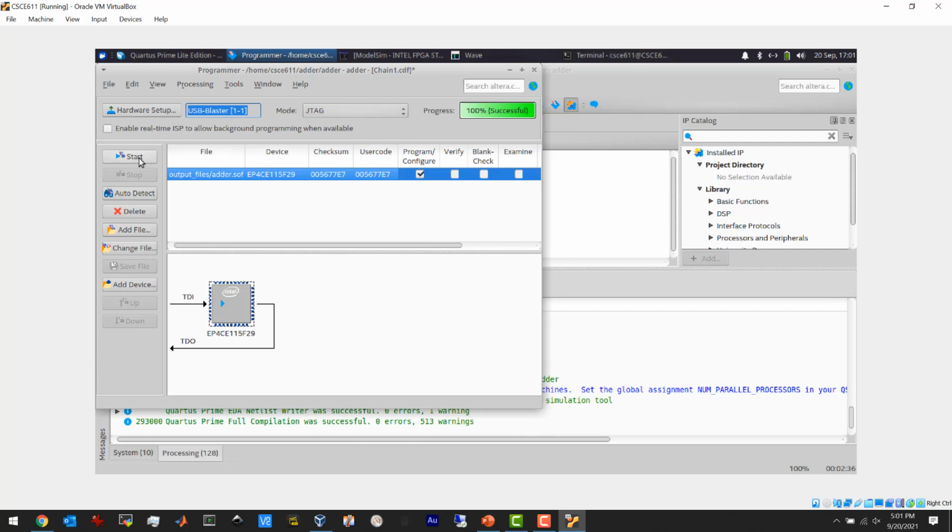Okay, so I'm going to flip switch 9 and 8 because those are the two least significant bits of A. And B is down here, so if I put, let's say, 5, 1, 0, 1, this should be adding 3 plus 5 is 8, and 8 represents 1, 0, 0, 0. You see how it's hard to tell, but yeah, you see that light is on.